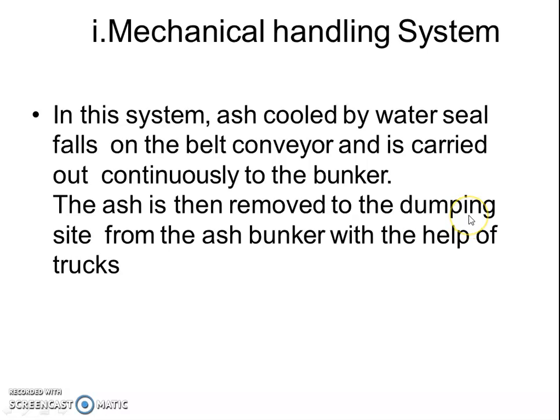Mechanical handling system. In this system, the ash, cooled by a water seal, falls on the belt conveyor and is carried continuously to the bunkers, and the ash is then removed from the ash bunkers to the dumping site with the help of a truck.